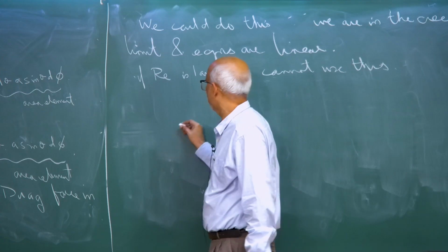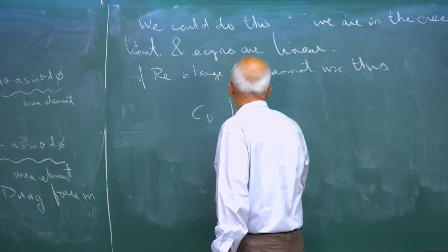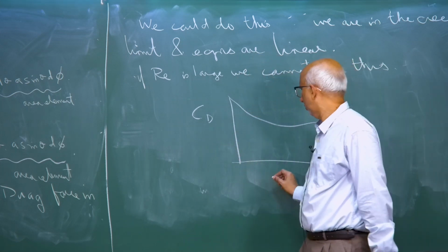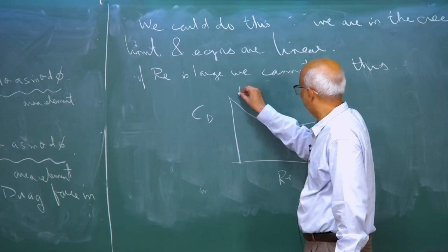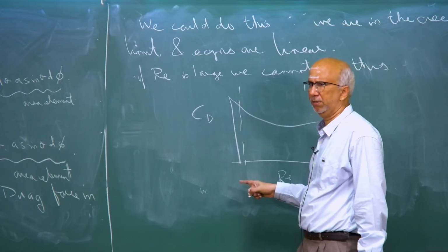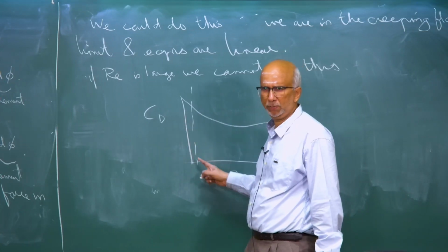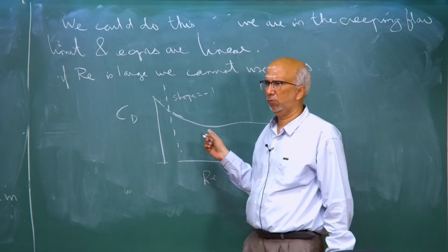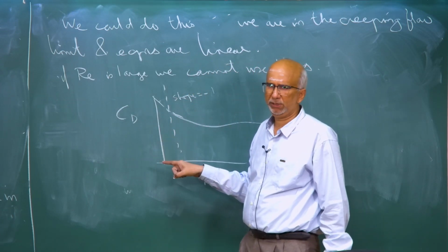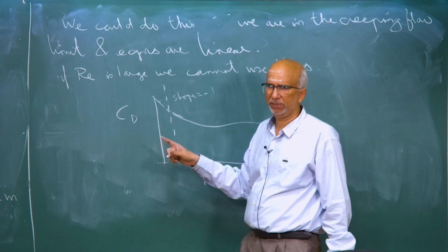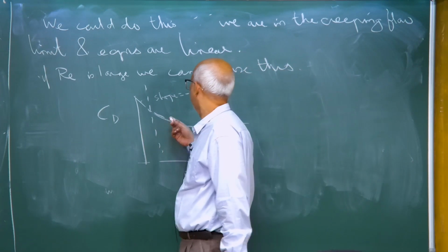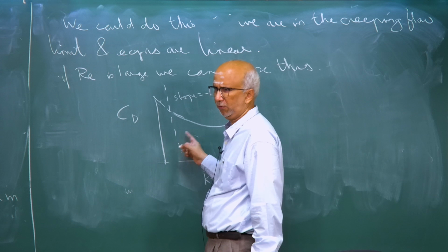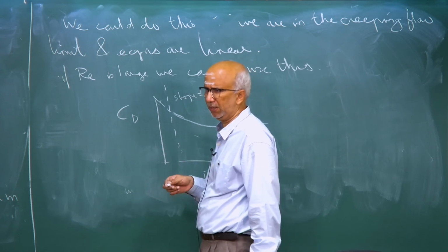And then what you do is, you have these charts which you must have used in your undergraduate somewhere, some curve like this, and for a particular Reynolds number, as long as you are in the low Reynolds number limit, this is a log plot. So, the slope is -1. You can do some experiments, calculate what this drag coefficient is, and then you can calculate what the force is. This is valid for small Reynolds number. If you want, you can extend it to some extent and maybe try to push your luck, but for large Reynolds number you can't use this. Okay, keep that in mind.